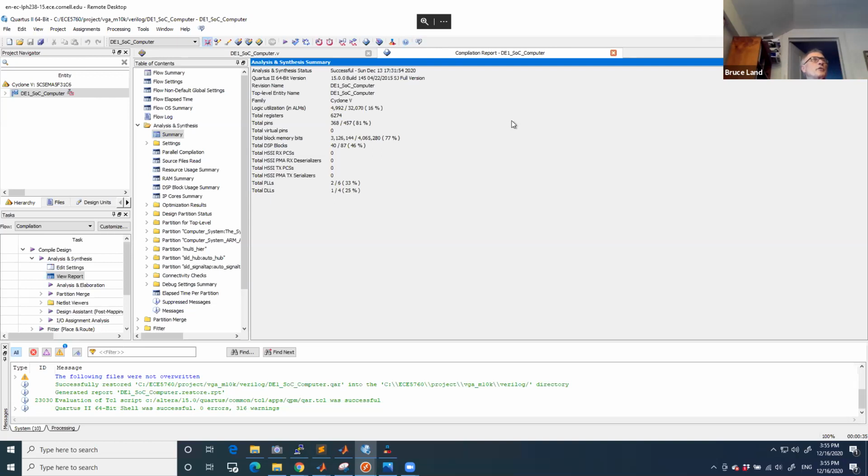The only other thing you can do is output two signals plus a trigger on I/O pins directly to an oscilloscope and debug using the oscilloscope rather than SignalTap, which requires no memory. It does require physical access to the FPGAs, which we couldn't manage this semester. Also, you can only look at two signals at a time, so you have to think very carefully about which two signals are most important. You could compile with 20 signals being output, but you can only look at two at a time, plus a trigger.